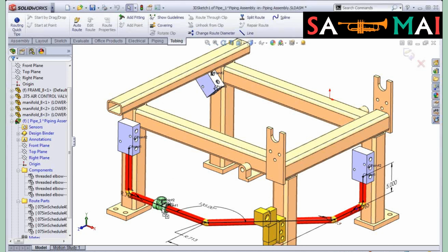When I drop it on here, wherever I drop it on the pipes, it's going to automatically orient and mate itself, if you want to call it that. Orient itself to these pipes and snap into place. It will also automatically split this pipe into 2 pipes. Now, I still haven't dropped it yet. I still haven't released the left button on my mouse. The tab key will give you 2 options, this way or this way. Neither one of those are the way I want.